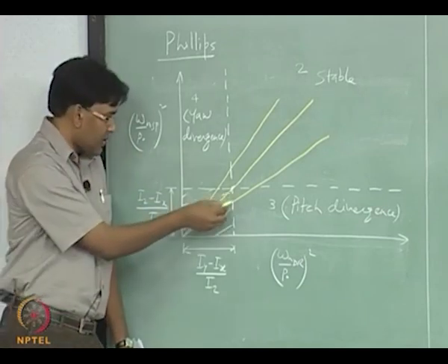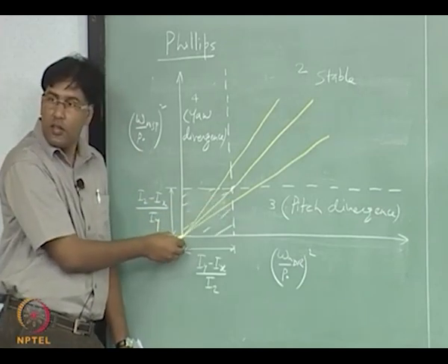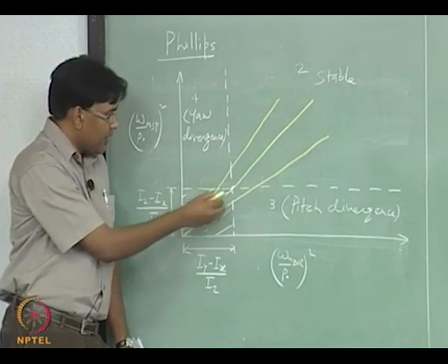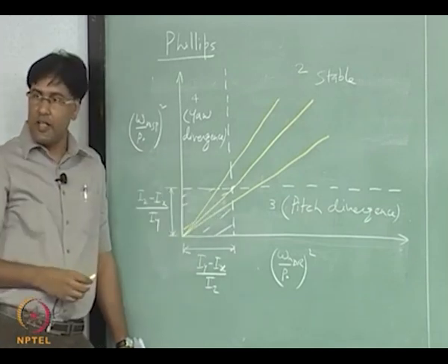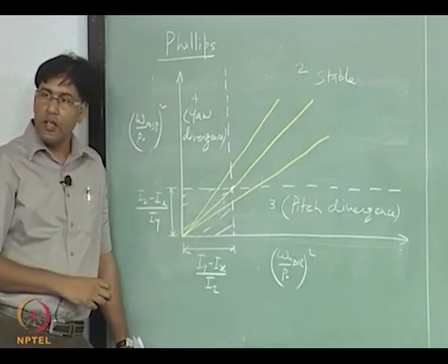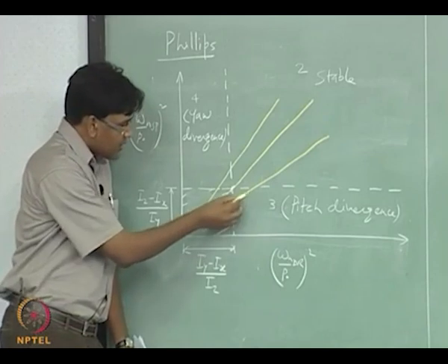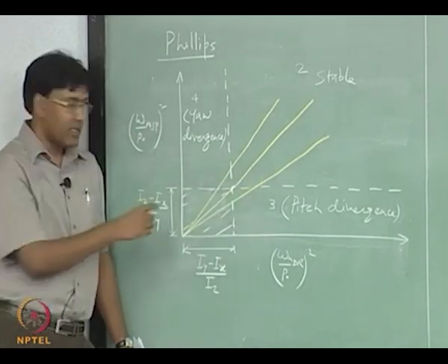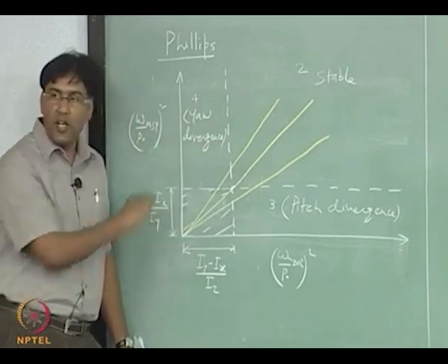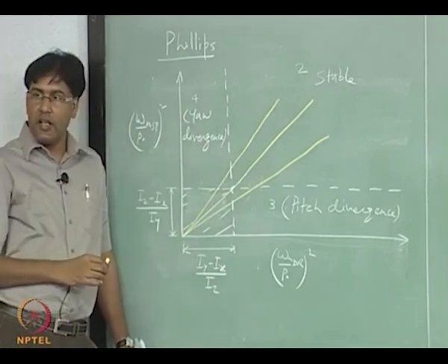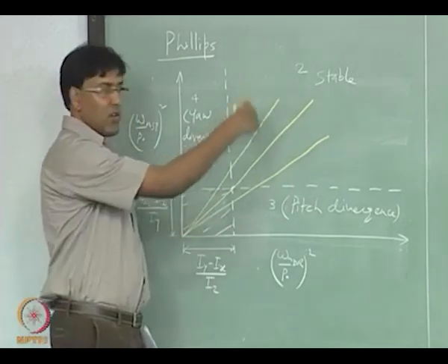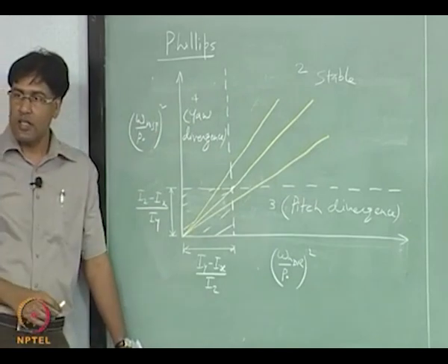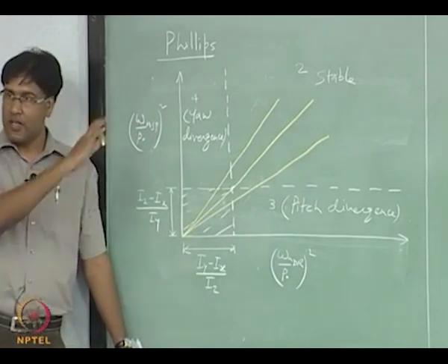So, starting from here, 0 roll rate, in this region the maneuver is stable. If you are passing through this, then you are going to see in this part pitch divergence, in this part you are going to see yaw divergence, right, and again in this part where the roll rate is quite high, it is stable, but under some conditions.